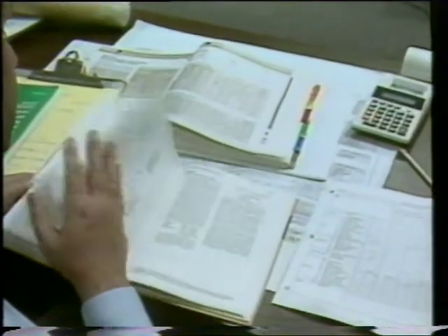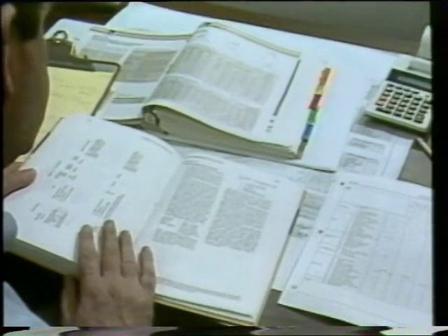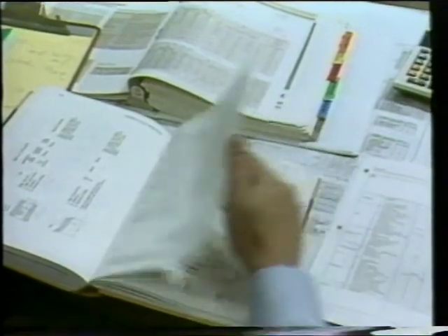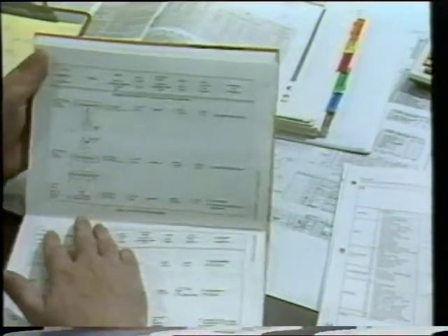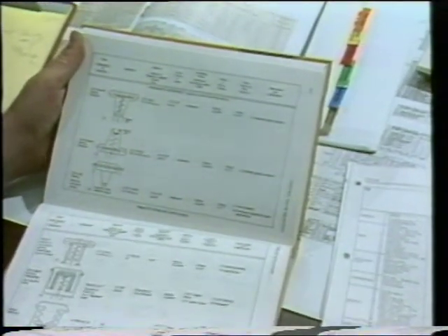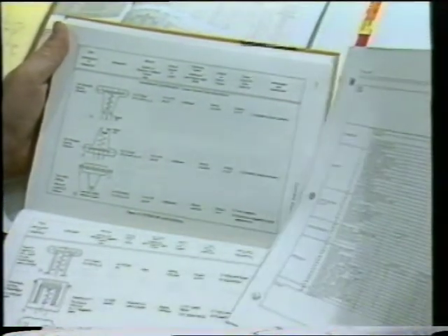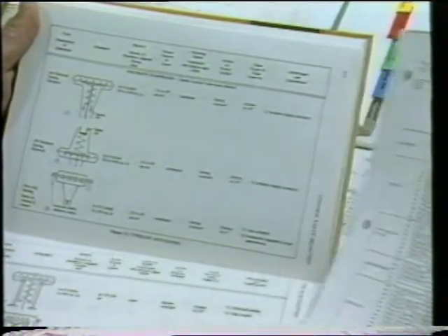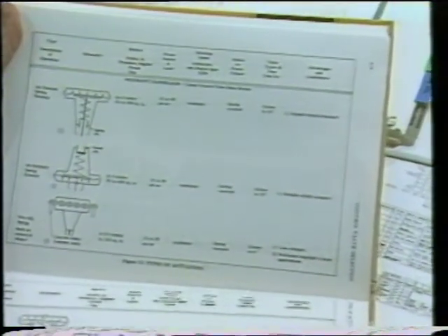After you've identified the power medium available, details of the various actuator styles in that category must be examined. Compare this information to the needs listed on your datasheet to determine the actuator type that will do the job. For example, suppose the initial choice is a pneumatic actuator.